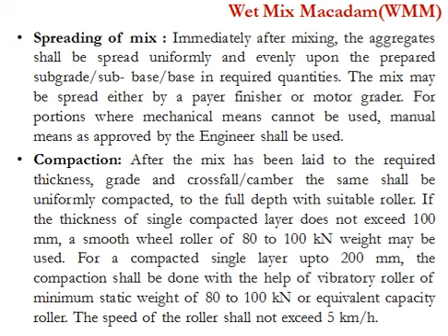The aggregates should be of uniform gradation with no pockets of fine materials. And if mechanical means is not possible for spreading the mix, then we can spread the mix uniformly using manual labour, but this should be approved by the engineer.